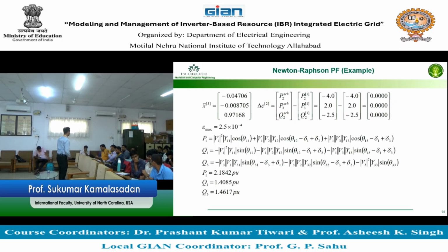Yeah, you got it. Now after that we have some data required for the distribution system. What is the number that you got? That is not the same as the other load number, right? It's different. So you multiply P and Q with a scale number and run it on the distribution system. P and Q are from the distribution system. Voltage is going to it. So the voltage you get, put it on the substation, the 2400.